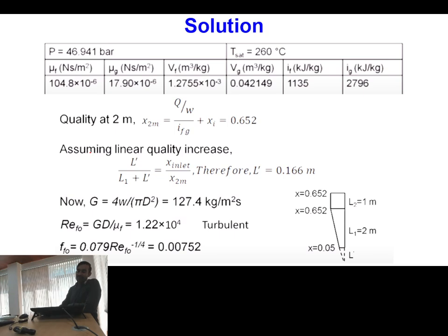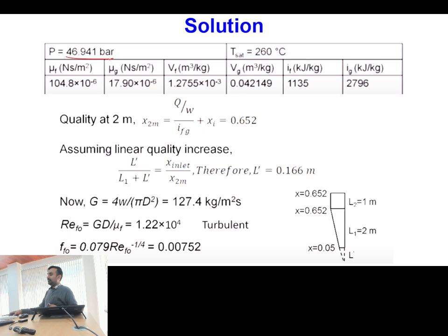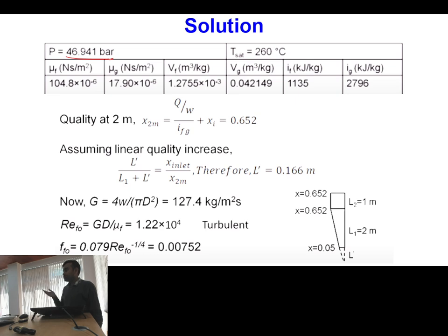So the very first thing we have to do is determine the properties. We have an air water system. I'll be going to the steam table, and of course when I am operating in the boiling regime, I will have liquid to vapor conversion. So I am operating in the liquid vapor dome, and I have to use the saturation state table.